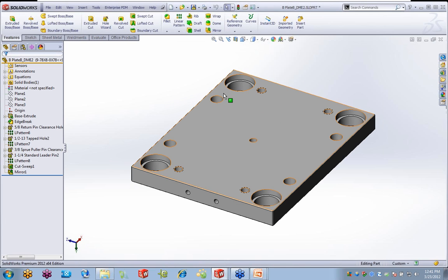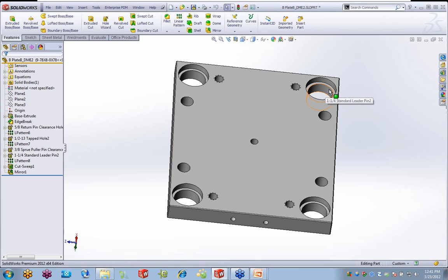I'll find it. Center marks and center lines have an option so that when you create the drawing view, you want it to auto insert on view creation the center marks and center lines. And the reason I'm bringing this up now is because the ability to create a drawing that's, let's say, half detailed for you without notes and so on is possible within this system.